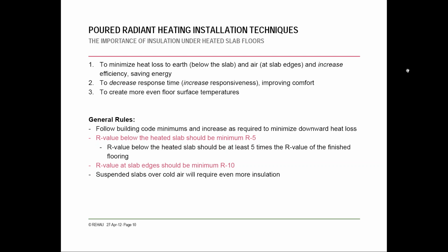Insulation underneath the floor is obviously first and foremost to keep the heat loss directed towards your space. So it's very important underneath, but it's most important at the edges. And in fact, ASHRAE's latest recommendations, as well as the new Illinois code, IECC 2015, both address minimums, specifically relating to the borders and foundations if you're on grade.